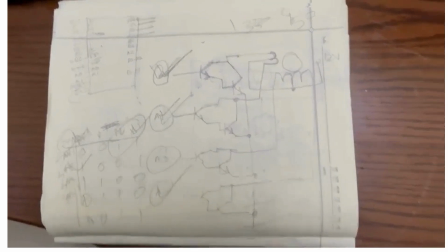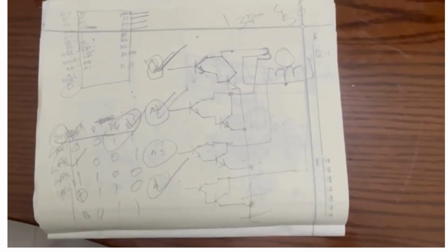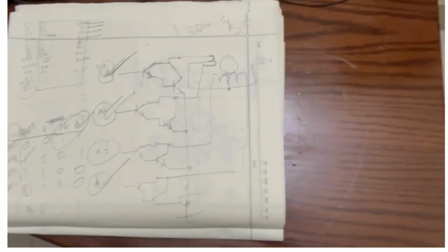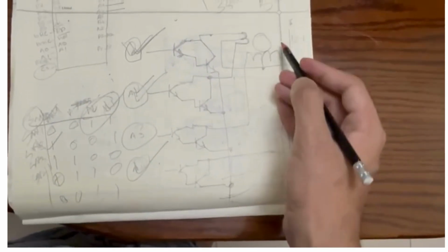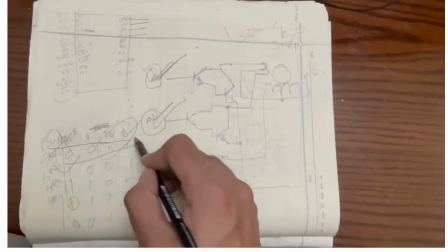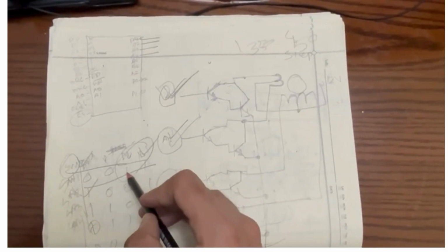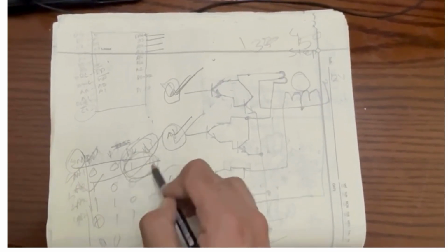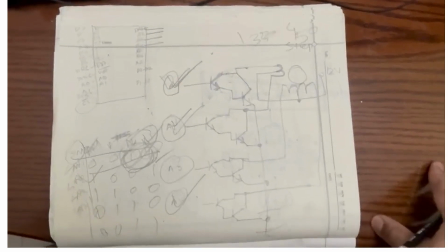So in the half step motor, the process is mostly the same. Just, before there was only one shift at a time. Here we are completing the overall shift, but when we are telling it to be a half step, there are 8 steps. How many steps are there? 4. We will convert these 4 steps into 8 steps. Here we are shifting 2 ones at the same time. These are not variables, they are 2 constant binary numbers at the same time.